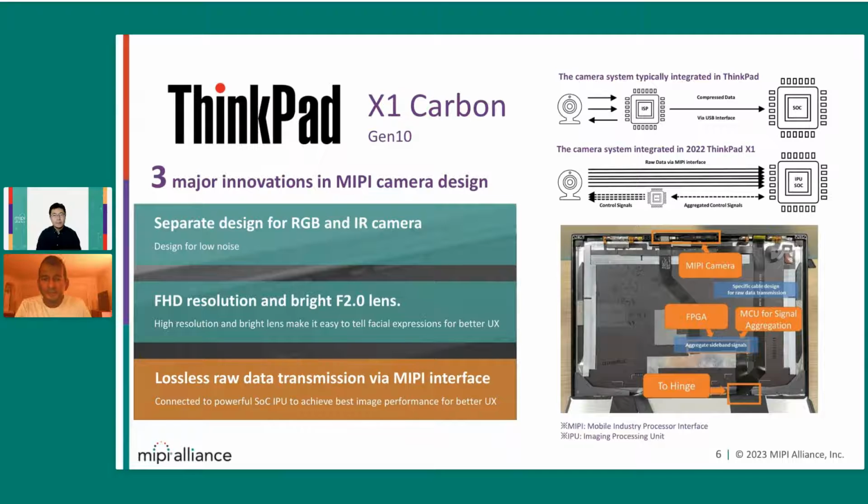Oh yes. I can see a great deal of doors being opened by the second approach, by leveraging the higher caliber ISP in the SoC. You also referenced the possibility of vision being used by leveraging AI engines. From that perspective, under the umbrella of ISP, we have things like lens shade correction, white balance, pixel defect correction, gamma correction. Do you envision the use of AI engines for things like scene analysis or denoising, demosaic, TNR as well?